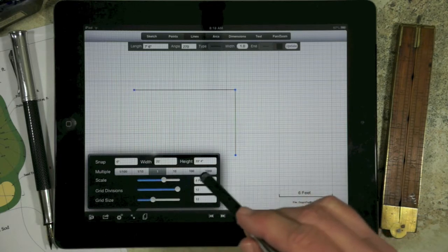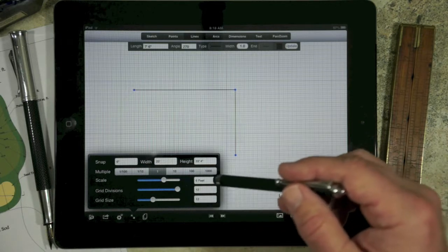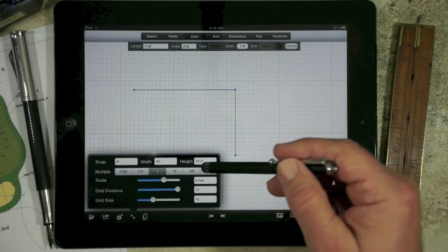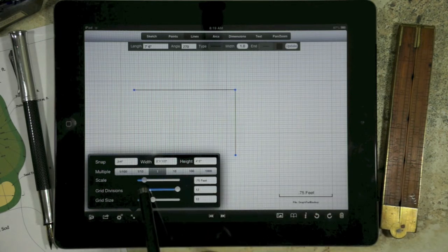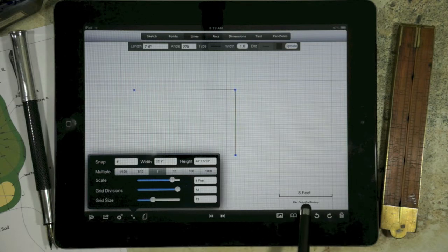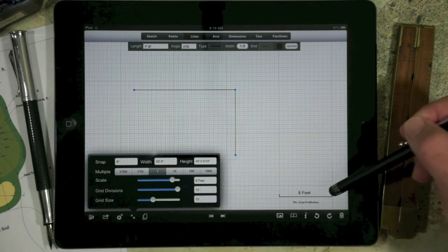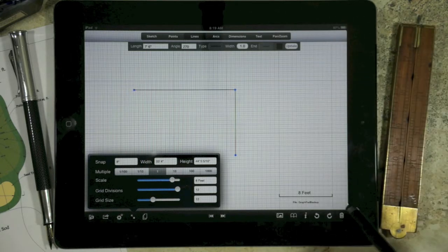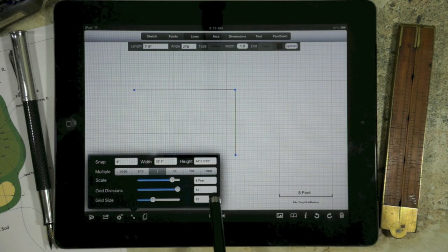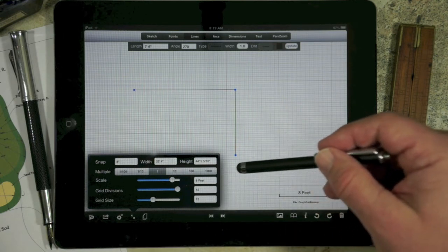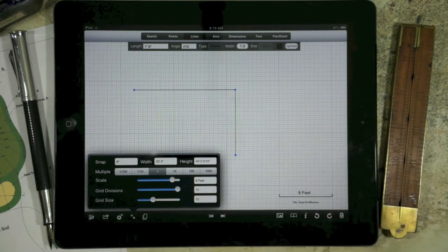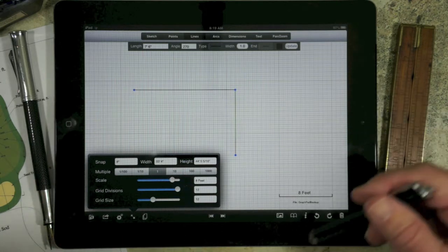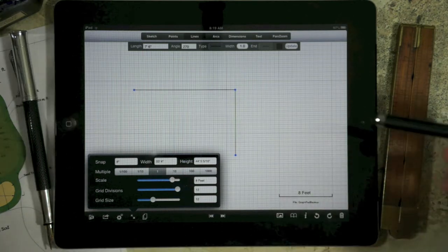We can manipulate how the scale works based upon these settings. So if we're completely far off and we need to do something that's in hundreds of feet, we can multiply it by 10 or multiply it by 100. We can set the scale, so this does it in a fairly coarse way. We'll notice down here in the lower right hand corner it shows for a large block it's 8 feet across. That makes our snap 8 inches across. And these are the number of divisions. When we're working in feet and inches, we'll almost always want to work in units of 12 divisions. If we're working in a metric system, then it's going to be 10. Architects like to work with 8 divisions.